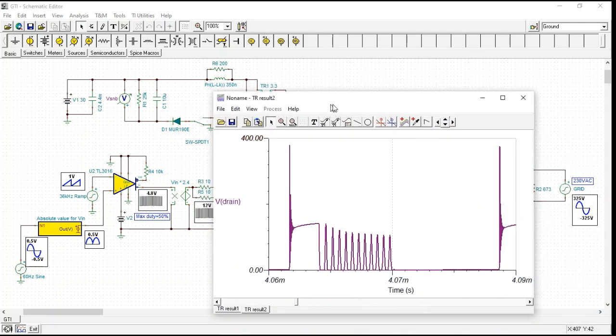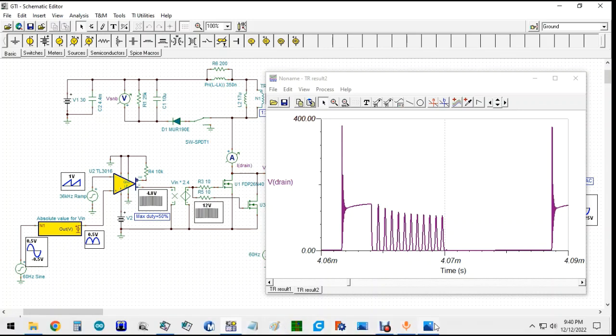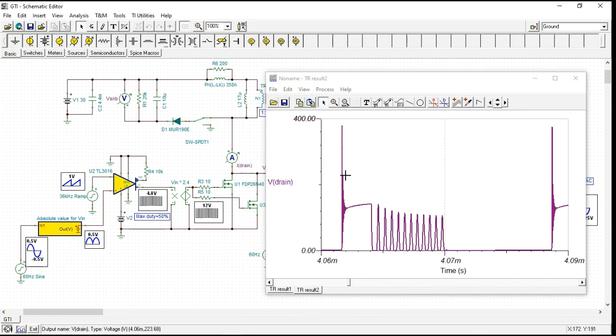So if I were to turn on and put the snubber in now, I want to try to bring down that peak, because I have 400 volt FETs here, and that would be uncomfortably close. Assuming I didn't know what it really was, and I had just simulated it for the first time, this would make me nervous. I would say I'm not happy with this. I want to get it down, at least maybe half that, 200, 250, somewhere in that range, which would be more comfortable than being that close to the limit.